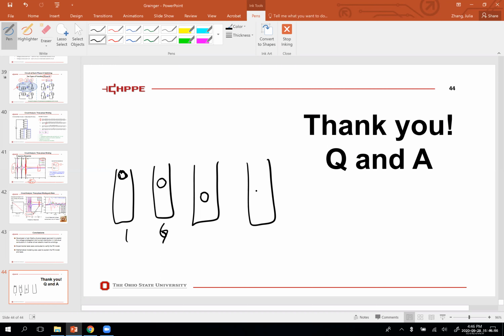Students may know those bar wound motors, like in the Chevy Volt, where all the conductors are square. They will try to have one wire go in the first layer, sometimes the second layer, sometimes the fifth layer, sometimes the sixth layer. So people already use that in production motors. Okay, thanks.